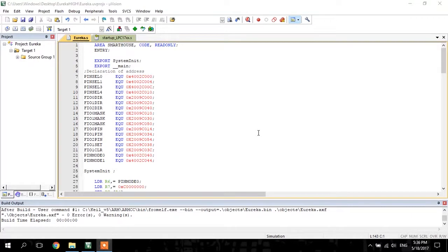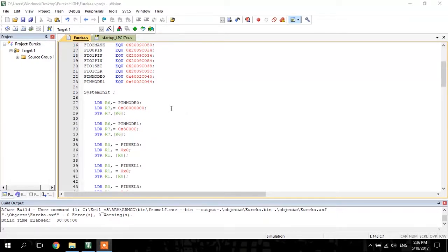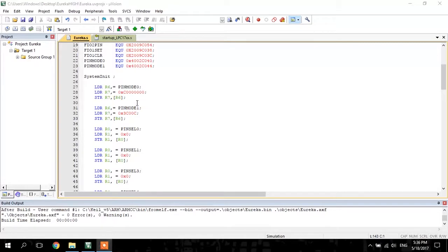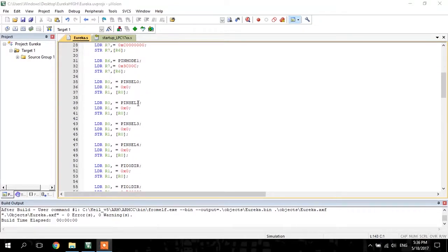We use up buttons of the joystick as the PIR sensor, down buttons as thermal sensor, left button as IR sensor, and lastly right button as the ultrasonic sensor. So as you can see, the ports we use are port 0, port 1 and 2. Port 0 is for input and port 1 and 2 are for output.